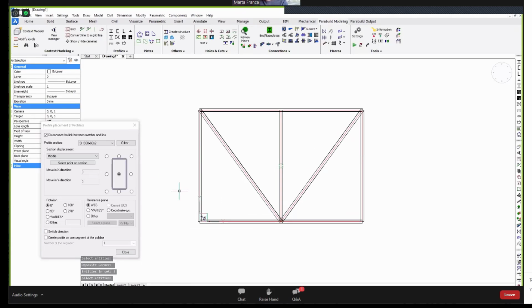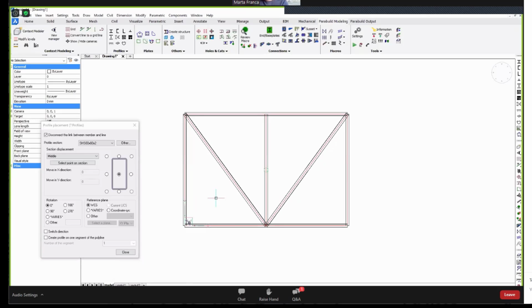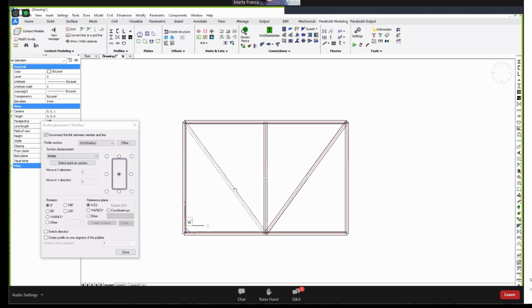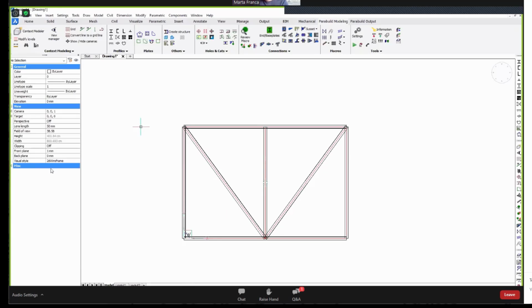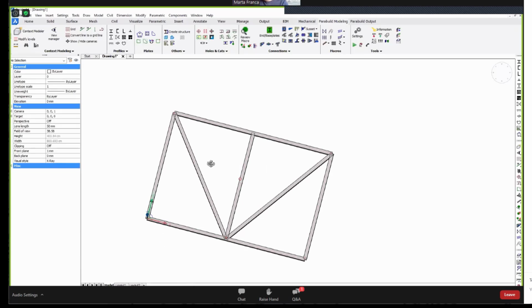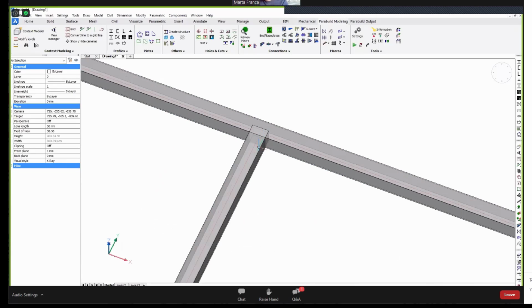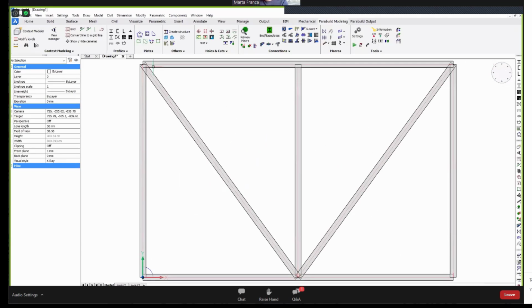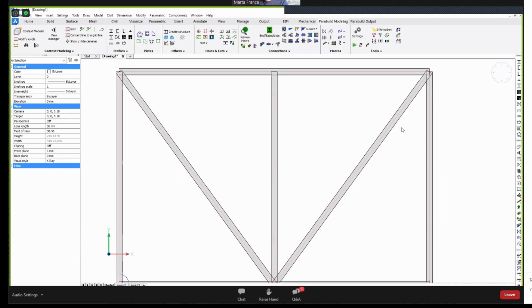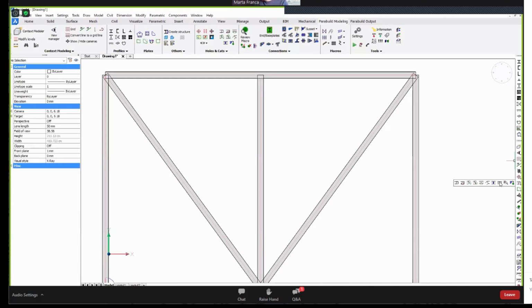So we can just select a number of lines, and on each line Parabuild then draws a profile on top of it. Let me switch to a better visual style so that you can see what I've just drawn. So let me start off with creating miters here at each corner. So there's a command for miters.